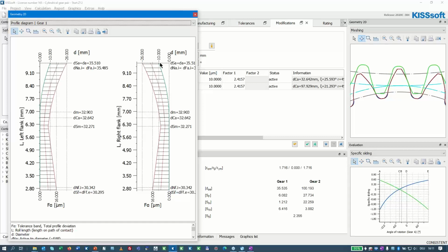You may have gears that are 10 microns. Sorry, let me explain first. You have a 13 micron distance here inside the tolerance field. You target 10. This means you will end up on average with 10 plus minus 13 divided by 2, which is 6.5.